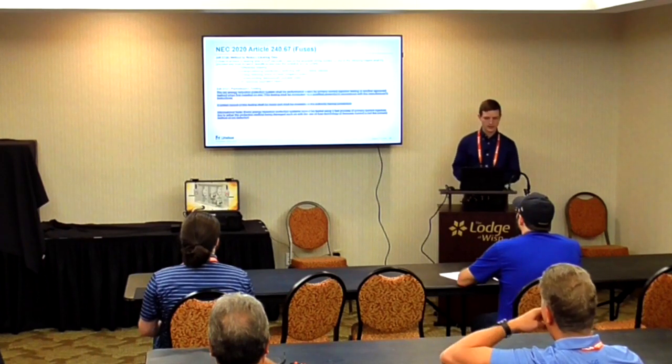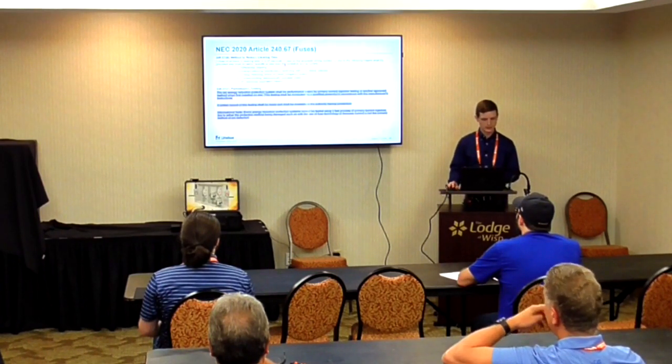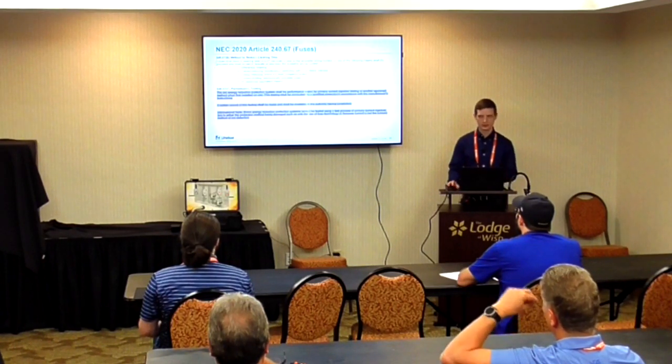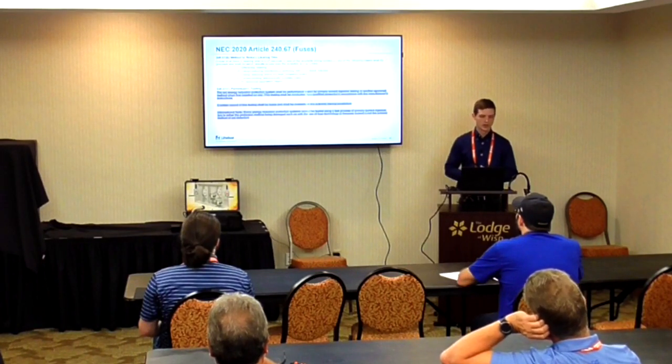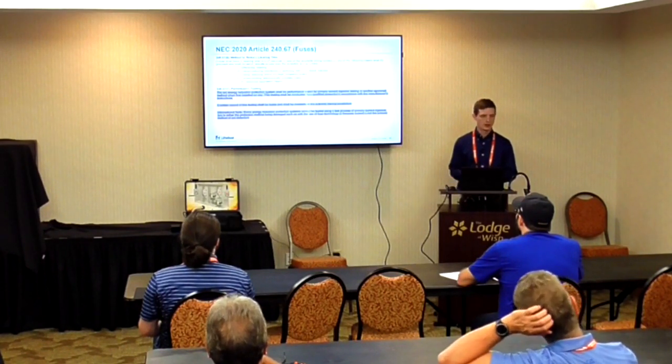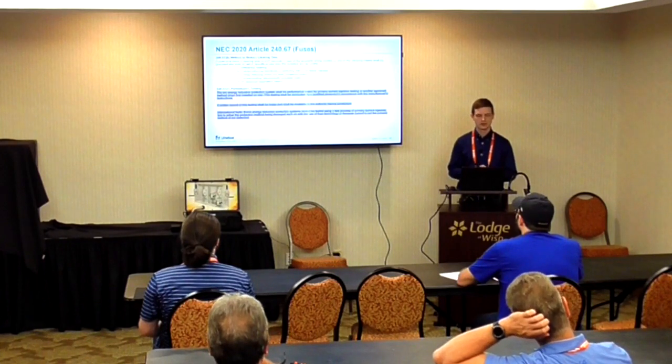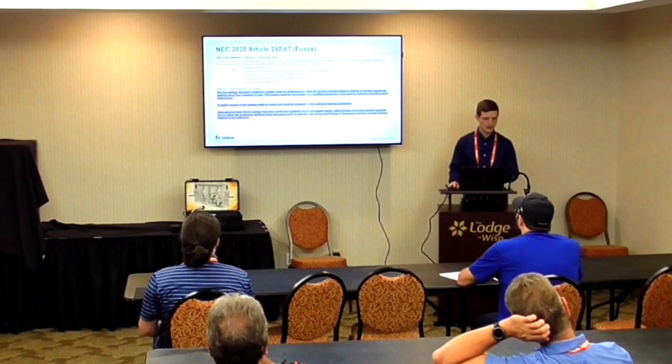And then you're going to have the second stipulation here, which is specific to fuses. So you'll see this a lot on like class Ls, those real big guys, or in class Ts, which are your fast-acting fuses. But it is the requirement to clear within 0.07 seconds. If your fuse can do that, you do not have to use any of these 5 other methods. You can just bypass that altogether.